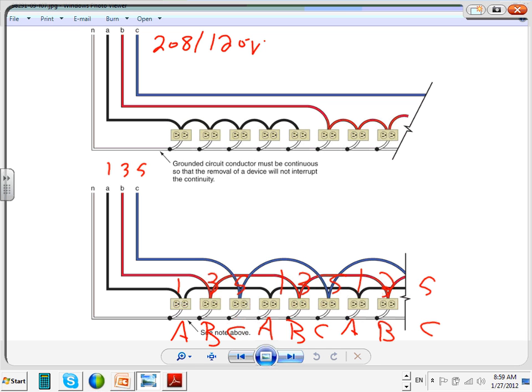Now this is expensive, as you can see, because the wires are going all over. A cheaper way of doing multi-outlet assembly or even wiring furniture, guys, is to use phase A for a group of them, 1, 2, 3, 4, 5, up to, remember we said up to 6 in our calculation. So in this case, it is 5 of them. Then another phase B here and phase C here, and that will make this circuit 1, this will be circuit 3, and this will be circuit what? 5. And granted, this will continue and all this good stuff.